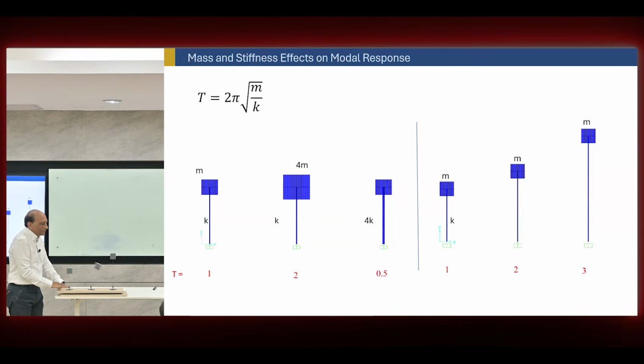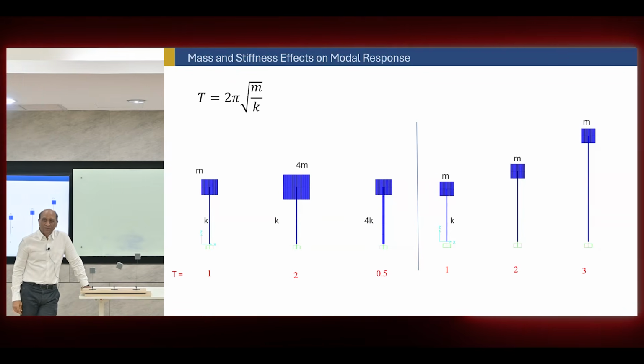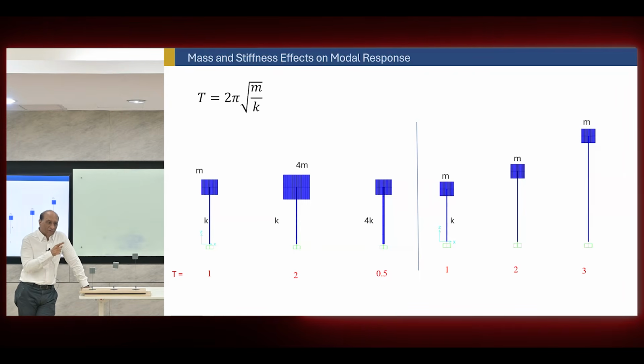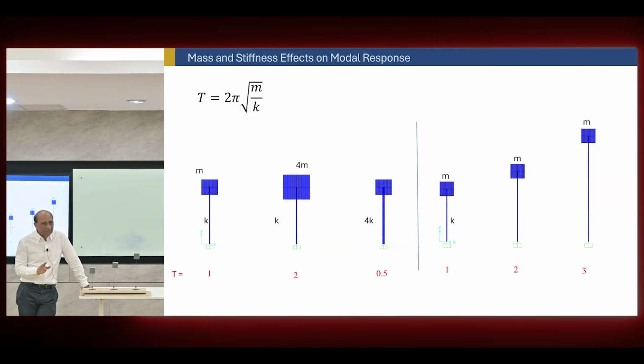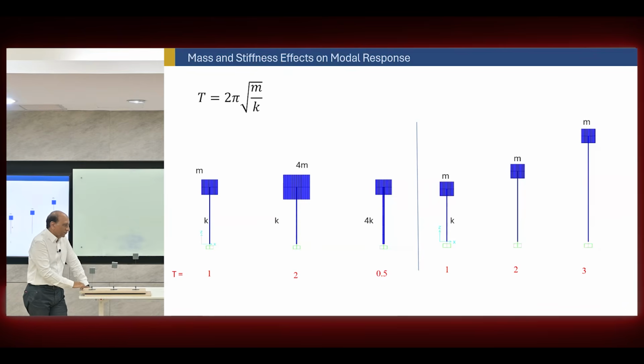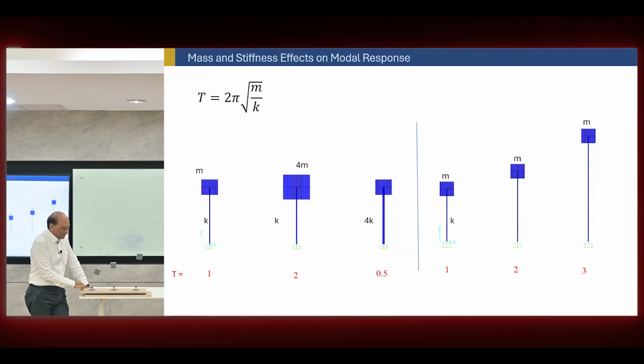So you can see, if this one is the natural frequency of that one, and I excite this one, only one will move. That means the natural frequency of the structure is the one that will respond to a particular ground motion if the ground motion matches with that exactly. And if I move it slowly, only that will move, the other will not move.